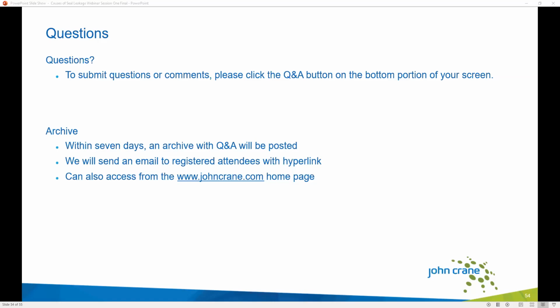So at that point, we'd also want to look at what are the operating conditions of the equipment at that point. If we can note down suction pressure, discharge pressure, the operational speed of the equipment, or if it's actually in a static condition, all of those pieces of information would be useful. And then whatever information we have about the process at that time, as far as the process fluid, the temperature, but also the process, if it's tied into a unit, what's going on upstream and downstream of that piece of equipment. All of that is very, very useful to help later on down the line be able to tie back into what we think the most likely and most probable cause was.